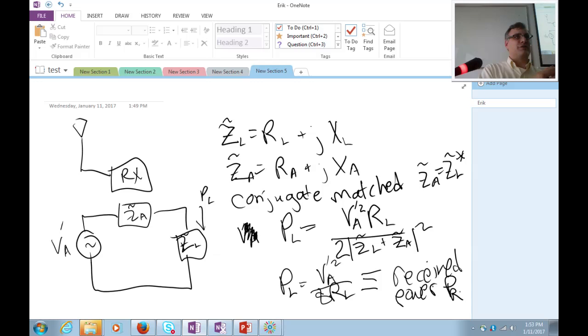Where does it reflect to? See, in the transmitter, it was very obvious to say where it reflected to, right? Because you've got a cable. You send power down, and it didn't have anywhere to go, so it came back. What about as a receiver? Where does the power go? It's reflected to the air. Yes. It re-radiates according to the pattern of the antenna in every direction, weighted against the gain pattern. Now that's a problem. You've just wasted communication power.